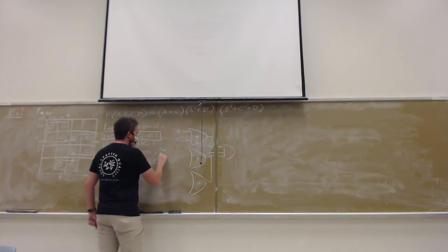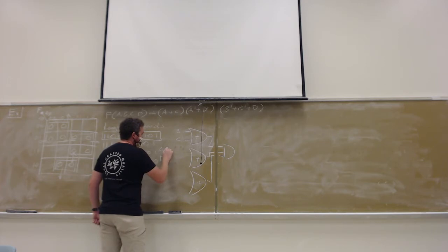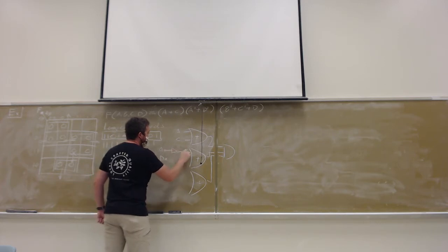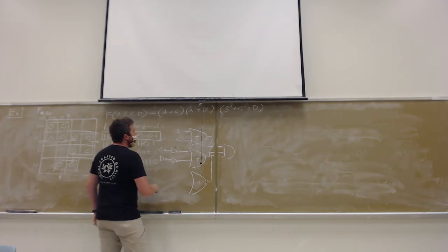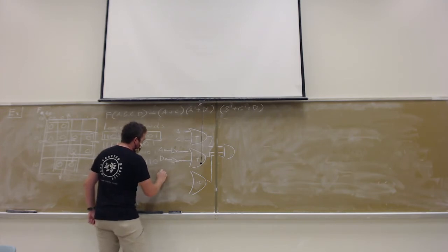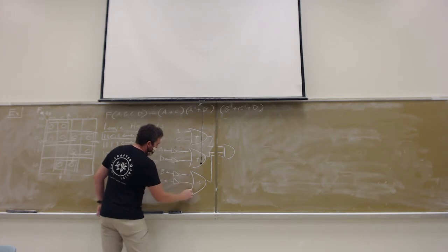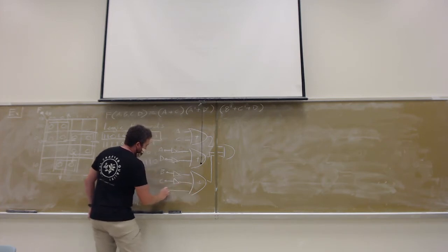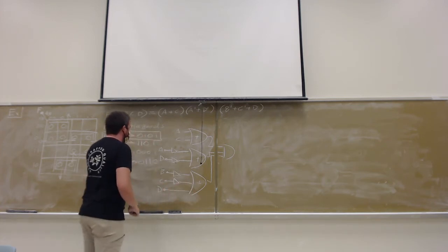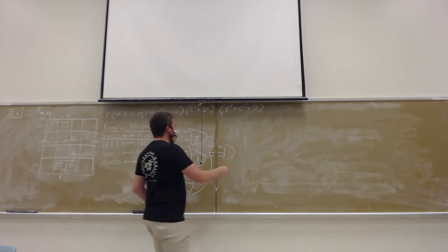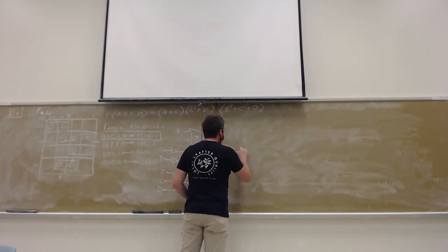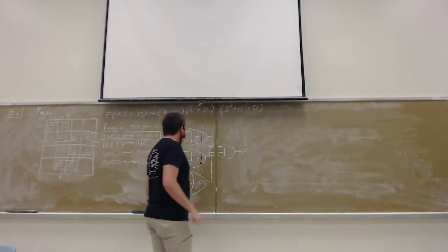So we've got A and D, both of which are going into an inverter. And then here we have B prime, C prime, and D, so it's going to be B and C, both through an inverter, and then D without the inverter. We'll play the same rules, we'll still say it's 10 nanoseconds per gate.